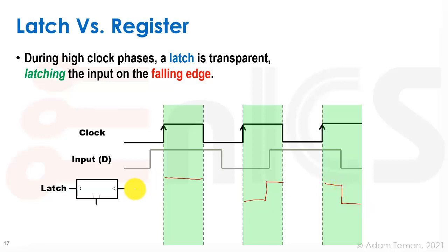At the areas where our latch is opaque, we're just going to keep the state that we were at prior to the falling edge. And we're going to have the transition once we open the latch at the positive edge. So we essentially sampled the latch here at the falling edge of the clock. We locked in what was there. So again, here's the falling edge of the clock. We lock in what is here, and we copy that along. And as we can see, this is the waveform that we expected to get. So that's how we see how a latch works.